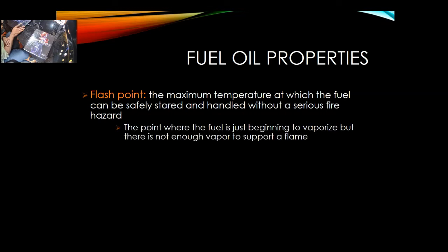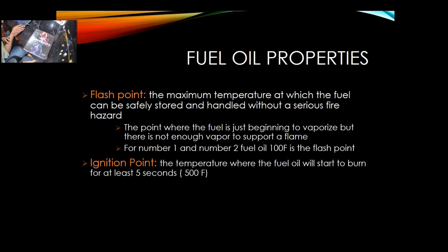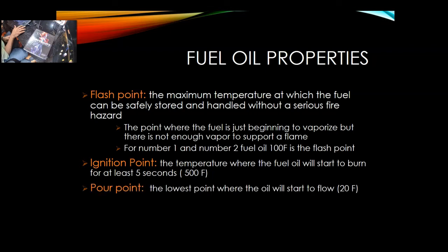Vaporize, but not enough to support flame. For number 1 and number 2 fuel oil, 100 degrees Fahrenheit is the flash point. And again, check with the book for different kinds of fuels. Ignition point is the temperature where the fuel will start to ignite and can sustain flame for at least 5 seconds. And that's 500 degrees for fuel oil.